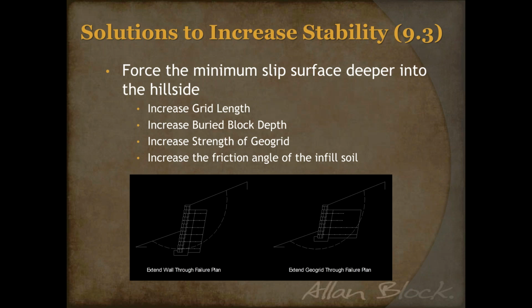As for seismic considerations, I have seen 1.1 as the minimum. That's pretty much been the consensus, but I'm pretty sure there's a range in there as well, probably from 1.3 to 1.1. So you've run your analysis and you found out that the safety factor for your global stability is below the minimums. How do you fix it? How do you change your wall design to address that and maybe get your safety factor to a higher level?